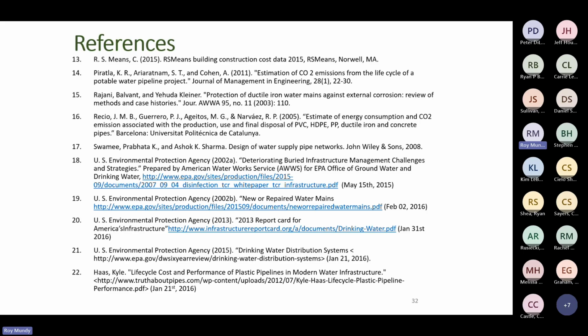And on the other hand, engineers also, and I'm an engineer, so I can say these things, they also use a Type 5 trench when speccing ductile iron pipe. Now, if it's under the roadway, it's got to be that way anyway, regardless of the material you use, because you're building a trench for the road. But if it's in an area where that is not a concern, if you put ductile iron pipe in a Type 5 trench, typically you're spending too much money. You don't need to do that. You don't need a Type 5 trench.